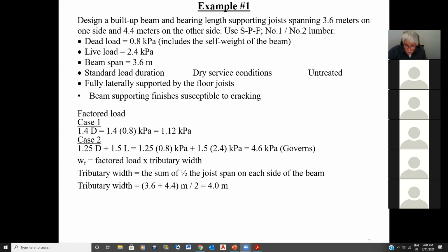And guys, like I said, this is only for structures where all the members are simply supported. Keep that in mind. Because the real tributary width, if you want the definition, is from point of zero shear to point of zero shear. And when things are all simply supported, where is the point of zero shear? At the center, where the moment is maximum, and that's where we take half and half. So this only applies for simply supported members.